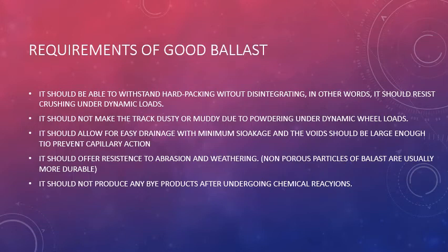It should not make the track dusty or muddy due to powdering under the dynamic wheel loads. It should allow for easy drainage with minimum soakage, and the voids should be large enough to prevent capillary action. I'm sorry, some spelling mistakes are there in the PPT. Extremely sorry for that. It should offer resistance to abrasion and weathering. The non-porous particles of ballast are usually more durable. It should not produce any byproducts after undergoing chemical reactions.